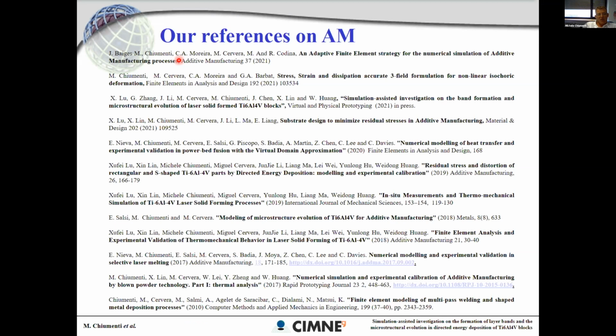So if you want to run a mechanical simulation and get accurate results, what we typically do is to keep very much refined the last 3, 4, even 5 layers, where the historical variables are affected, say plasticity has an effect, and then the rest is coarsened.